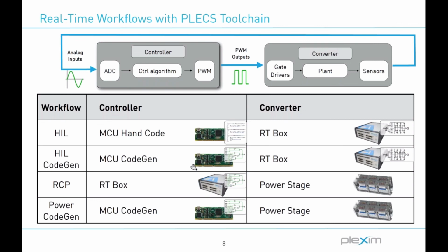And just to add on to that, James, we also have the option to synchronize those PWMs with each other, as well as synchronize them with an external source. And so there's a lot of flexibility here in terms of how we actually use that, for example, in phase shifted buck boost converters and so on. So it is useful for those applications.